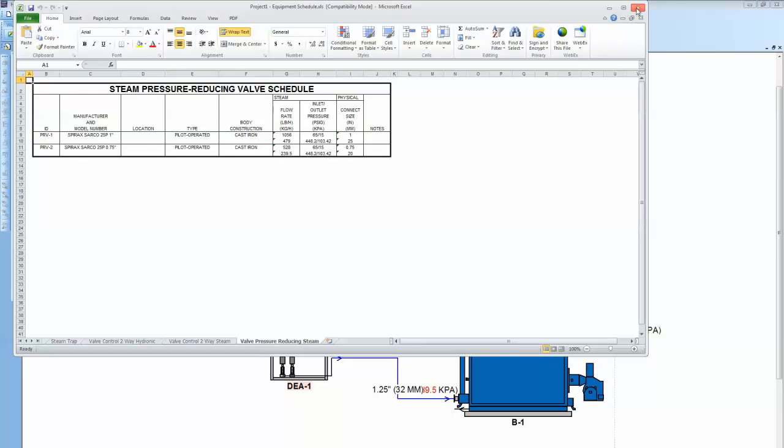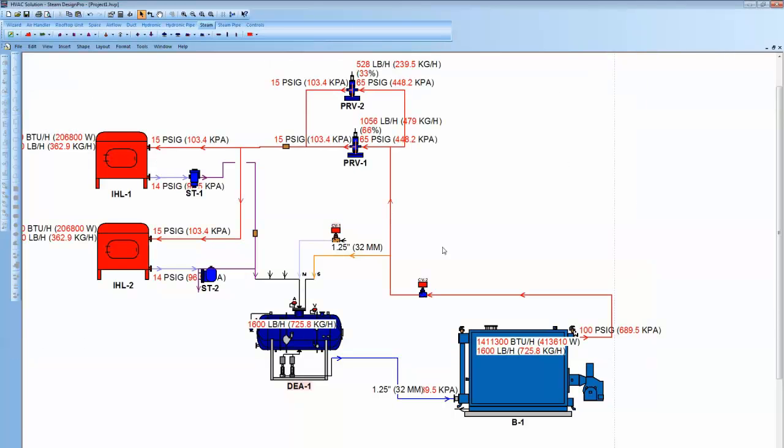One item just to note here, whatever's on your drawing here is going to be scheduled. You can schedule every pipe, fitting, valve, or you can go in the pipes and some of the components and you can turn things off if you don't want to create a schedule. Something might be new or something existing, you can do that as you turn it off.